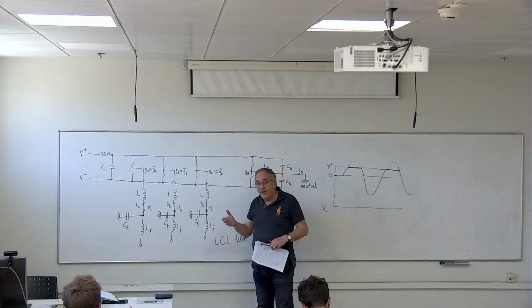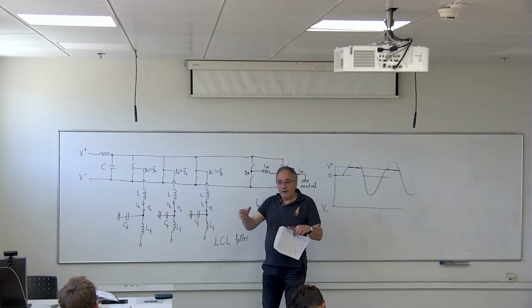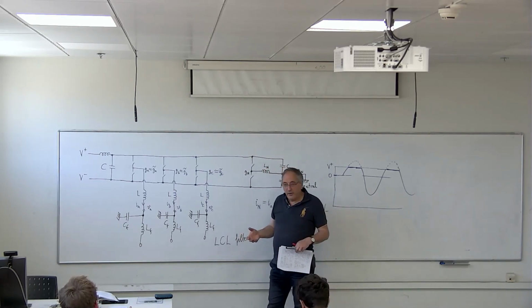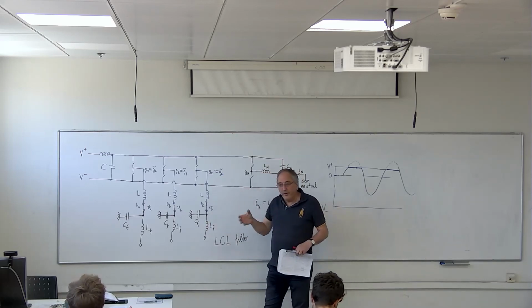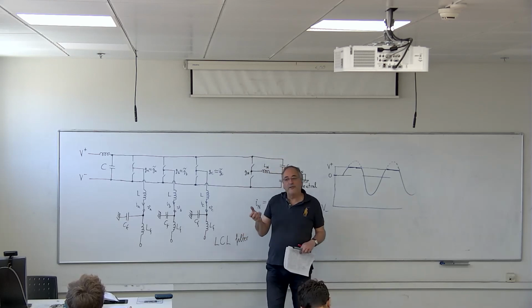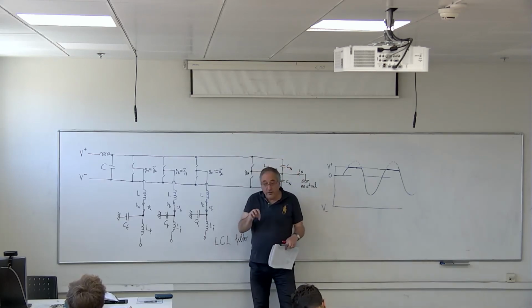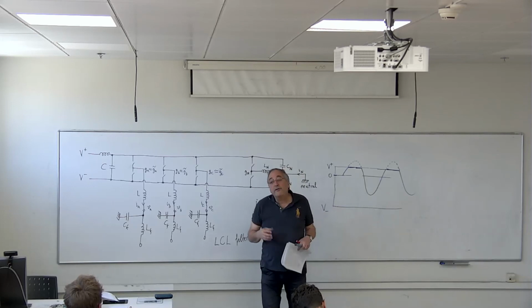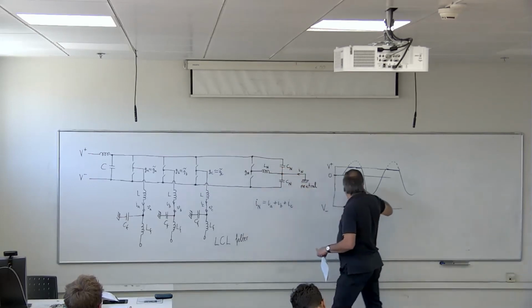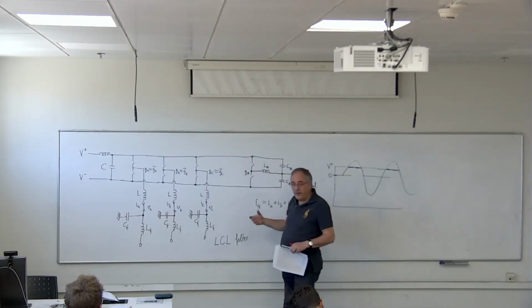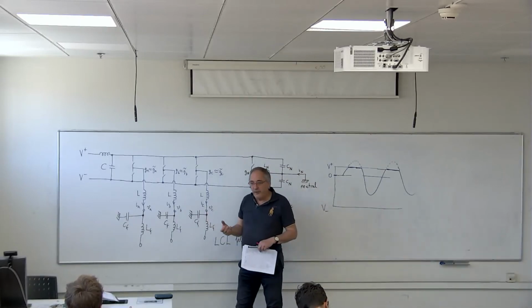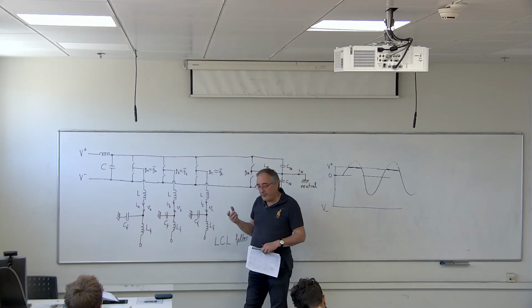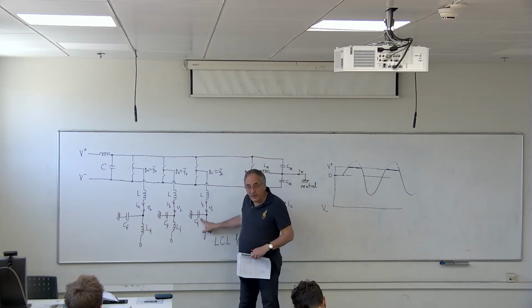So for example, inverters that operate brushless DC motors, they don't have the capacitor. They have only the inductor. Yes, because there is no need. The brushless DC motor, I mean the synchronous motor inside, does not care if you give it a highly oscillating voltage, because it filters it out by itself. The motor filters it out. So in the case of a brushless DC motor, the capacitor is not needed.